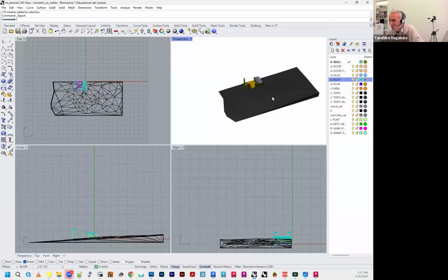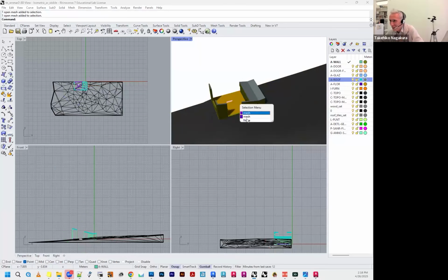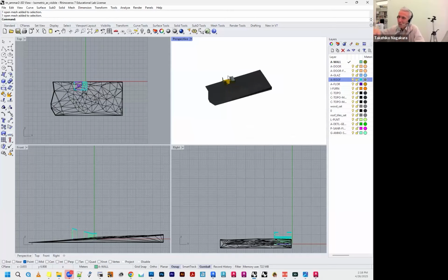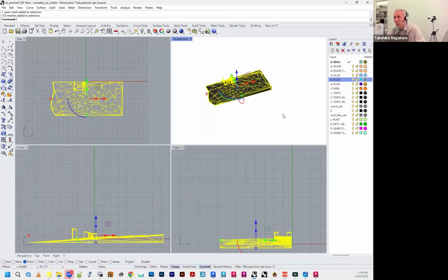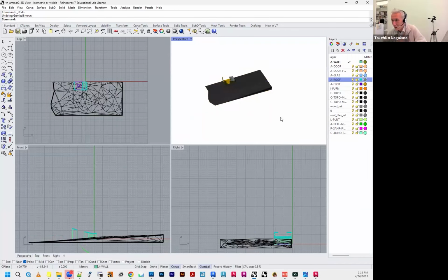And one of the things you may do is, there are objects here like roof and floors, and you import multiple DWG files from Revit and try to operate on them at once. You may want to actually group them, right? So you can actually choose everything in one shot, and that's no problem.